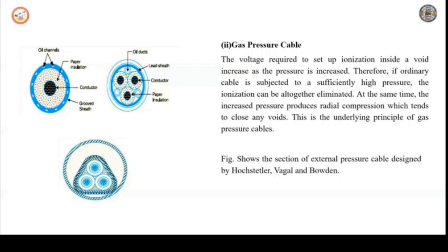During heating, the cable compound expands and the sheath, which acts as a membrane, becomes circular. When the cable cools down, the gas pressure acting via the sheath forces the compound to come back to the non-circular normal shape. Due to good thermal characteristics, fire quenching property and high dielectric strength, the gas SF6 is also used in such cables. This is about gas pressure cables.